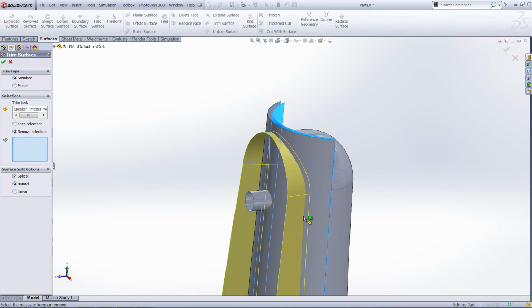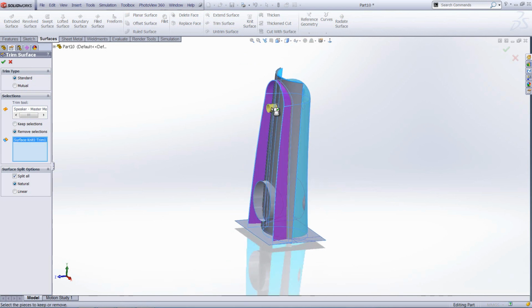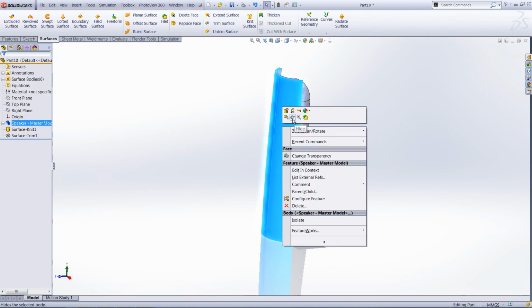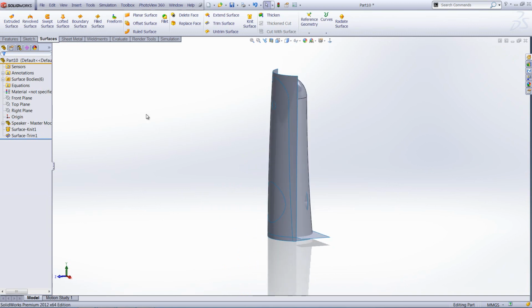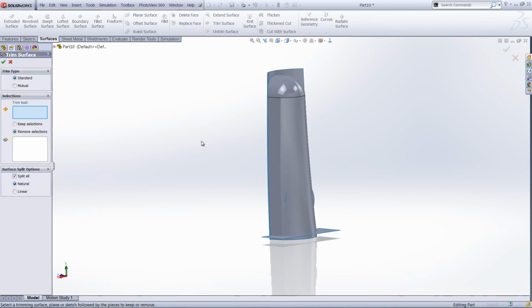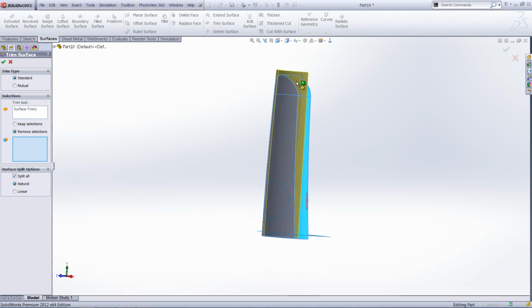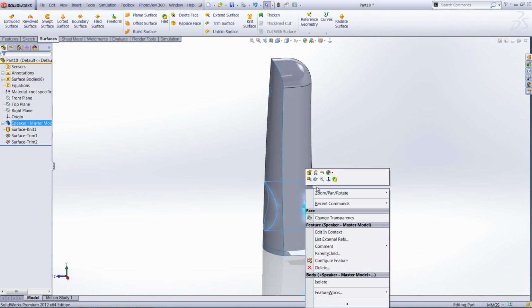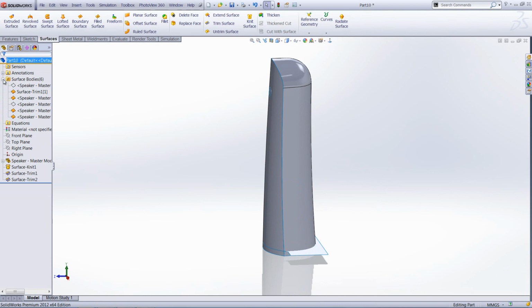So trim tool is going to be here, and I'm just going to go through removing all this information. Any bodies that I don't necessarily need, I can just hide them. I don't have to delete them or trim them. I can just hide them away. And that's often the case with a lot of surface modelling that we do. We can just hide away particular bodies. Likewise, I can do the very same with these individual circular extrusions. I can merely just hide those away.